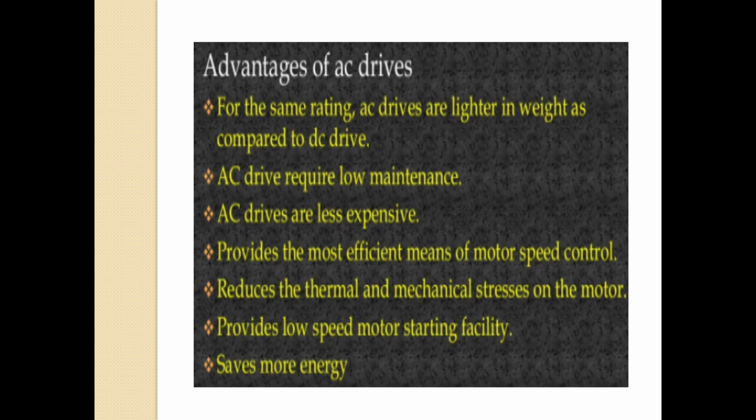Advantages of AC drives. AC drives of the same rating have lighter weight compared to DC drives. An AC drive requires low maintenance. AC drives are less expensive and provide a more efficient means of motor speed control. They reduce the thermal and mechanical stresses on the motor, provide low speed motor starting facilities, and save more energy. Thank you.